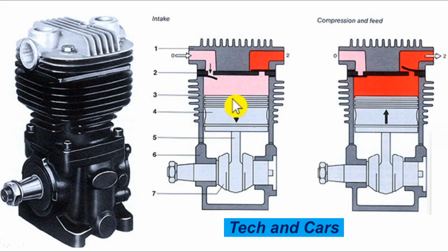If the compressor is not building up pressure sufficiently, either it is leaking via the piston ring and cylinder wall gap, or the intake valve might have some sludge or carbon buildup and not be sitting properly, causing leakage.